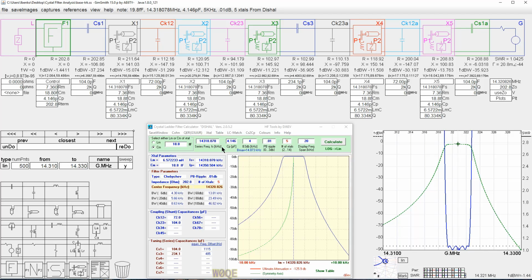Now, let's see how we could change this filter a little bit and see if we like it better or worse. You might say that passband ripple is awful small at 0.01 dB, and you'd be right, it is pretty small. So what we're going to do here is we'll make it 0.1 dB. And let's watch the skirts of the filter change when we do that. So we gained about 5 dB here, and we gained a couple dB here. And that looks pretty good.